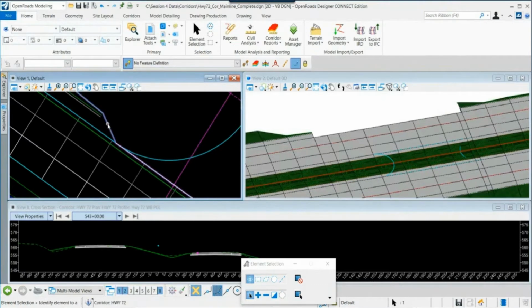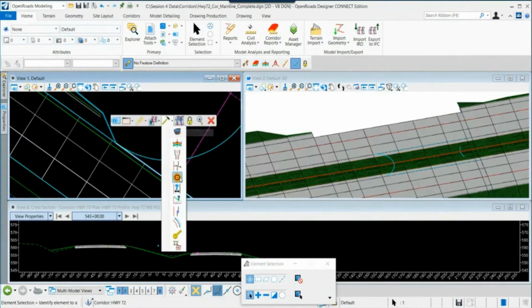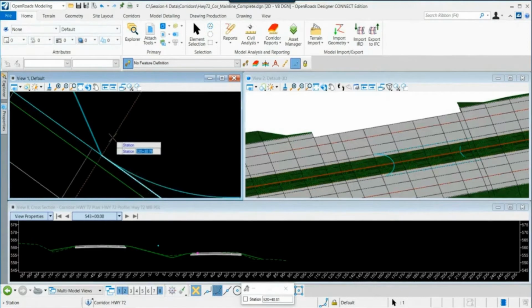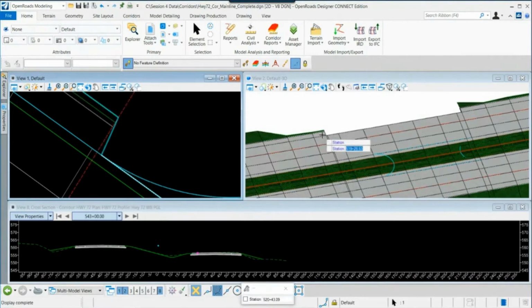So I'll select the corridor once more and select the key station button. Now I don't want this to occur past where the intersection begins. I want this to occur slightly before. You could mark this off as 100th before the station if you want. It's not super specific, but you want it to be slightly before this point, okay? I want one final template drop before I get to that point, and you'll see how this is going to tie the model together as we go through this. So I'll add in that key station. You'll notice that it adds in an additional template drop, which again adds a continuation of my shoulder.